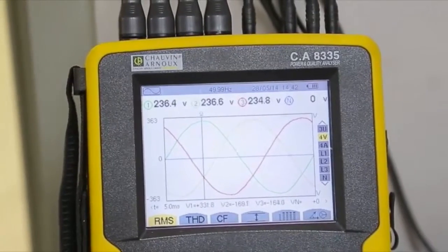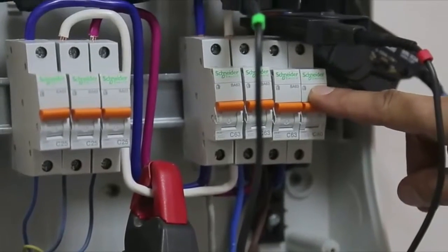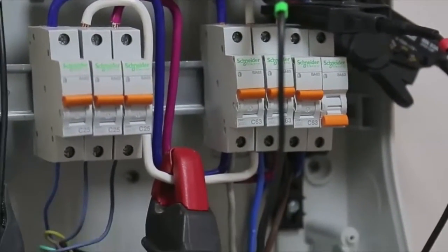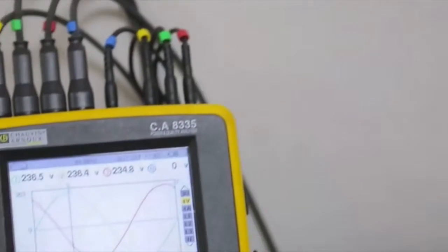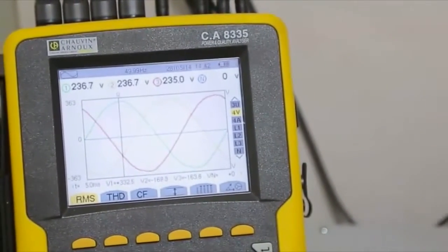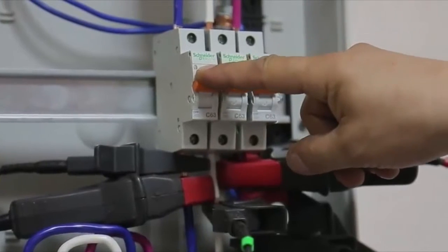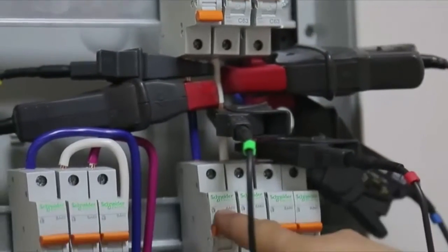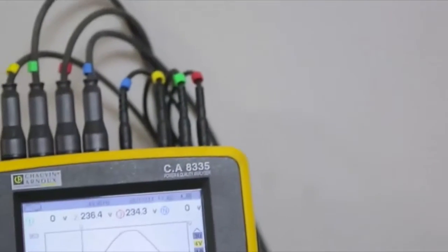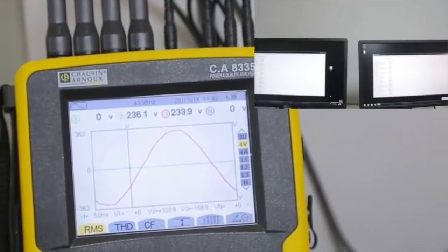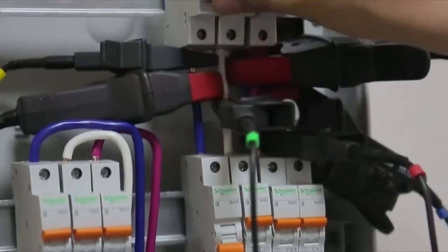Observe 3 voltages of the supplying grid. Disconnect neutral of the three-phase grid. No voltage change in the grid. Let's reconnect neutral. Disconnect phase A by 2 single-phase automatic circuit breakers. The measuring center shows no phase A, but computers keep running. Let us restore phase A.